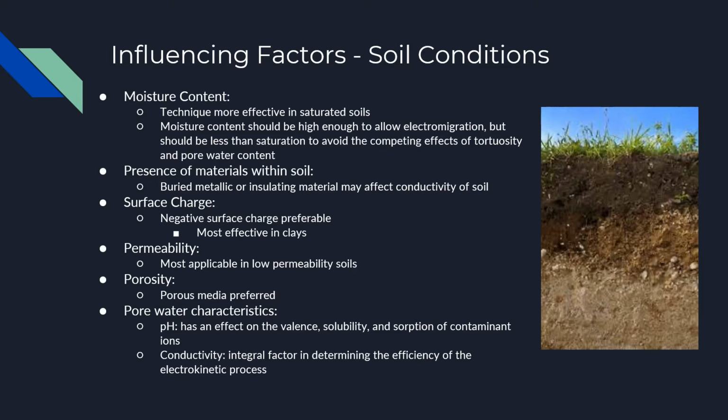For surface charge, a negative surface charge is preferable in the electrokinetic remediation method. This makes clays the most preferable soil type because of their negative surface charge. Electrokinetic remediation is also most applicable in low permeability soils, and a porous media is preferred.